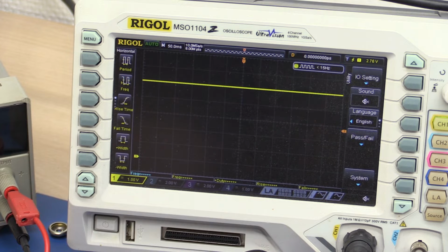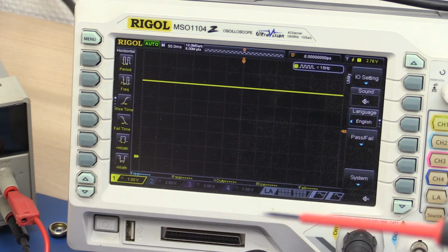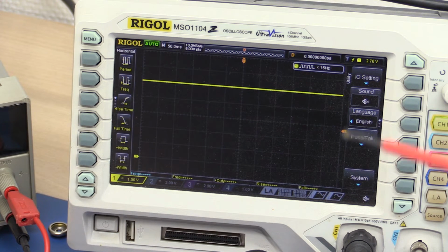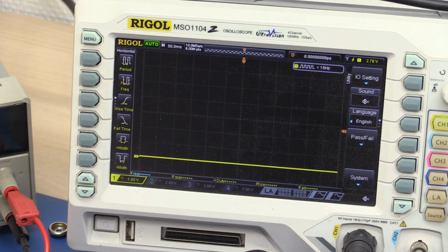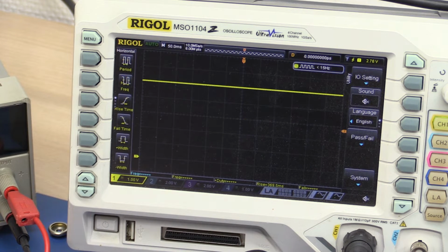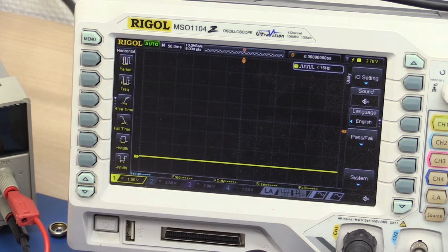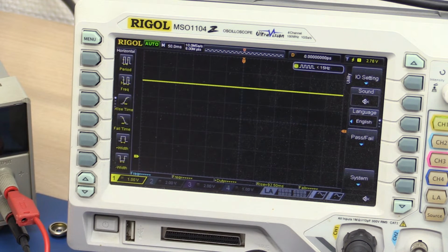Okay, so that's more like it. It looks like my resistor across the capacitor was actually doing more harm than good. I thought I picked a high enough value that it wouldn't really matter, but the problem is, as you saw, it allows the output to be a linear function of the input, which we don't really want. Okay, yeah. Yeah, now it works better.